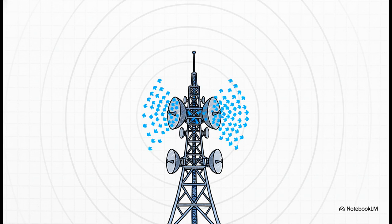And finally, we have MoM, the method of moments. This solver is incredibly efficient, especially for problems with a lot of open space, like an antenna broadcasting out into the air. See, instead of modeling all that empty space, it just focuses on the surface of the object itself, calculating the electrical currents flowing right on it.